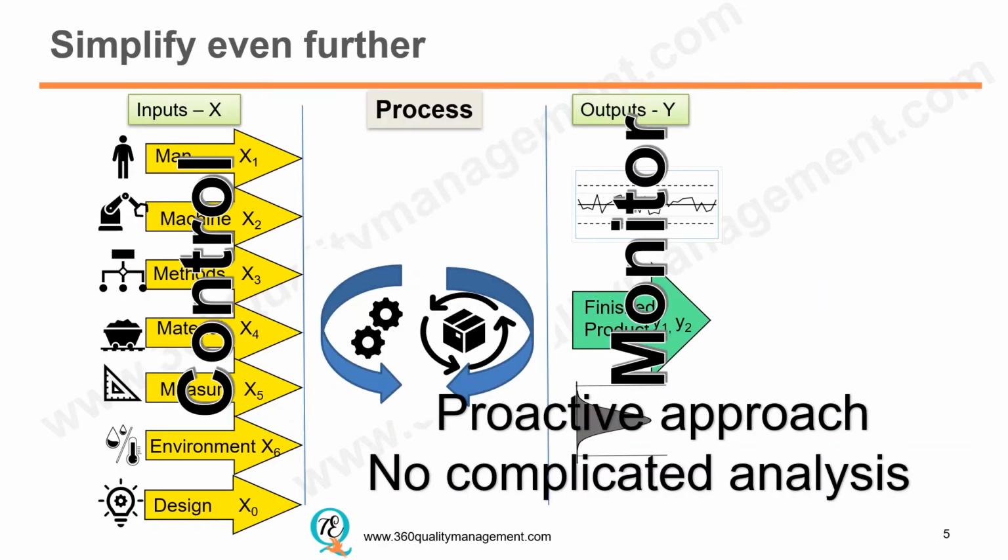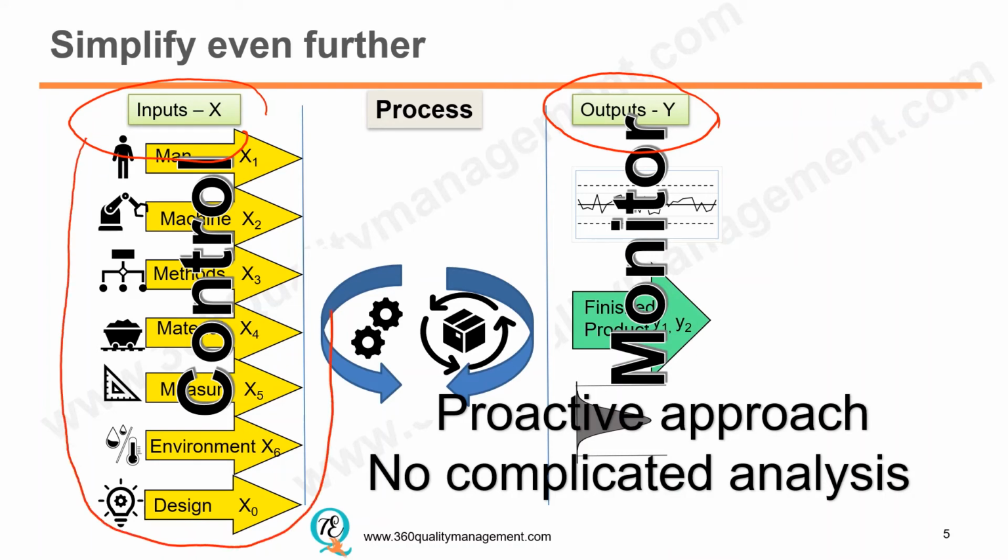I've simplified even further for you from the 7 steps just now. Basically, a consistently good process input will result in consistently good process output. Remember, garbage in, garbage out. Each process input must be set up and controlled correctly to achieve the desired process output. Therefore, controlling these process input variations should be the main focus to ensure a stable process output.